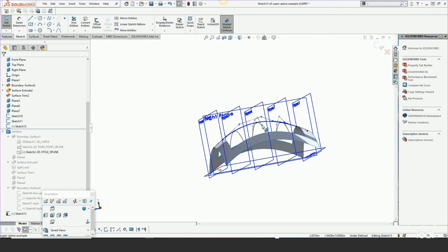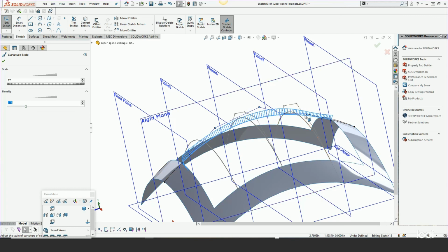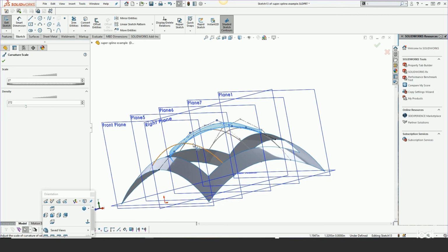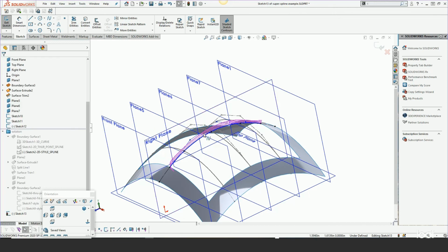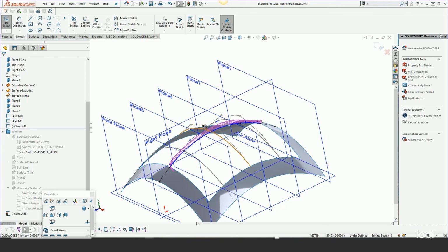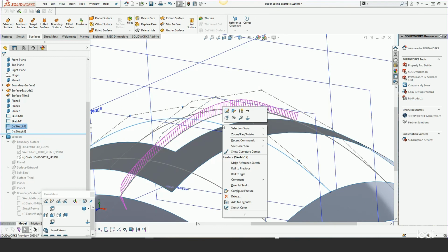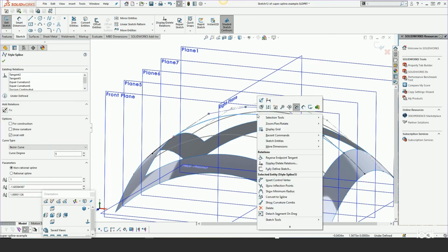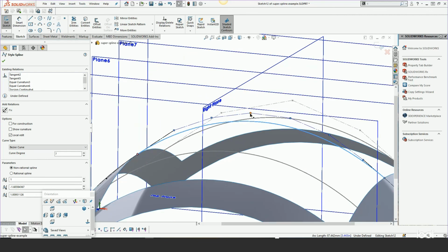Okay, so now we have a style spline with all of its smoothness, and we can do a little more tweaking like right there, but it's actually constrained to those existing points like a through-point spline would be. Okay, so now we have something that we can work with, and we might want to go back to this spline and, like I had done, put a little bit more degree of freedom in it, and kind of raise this up.